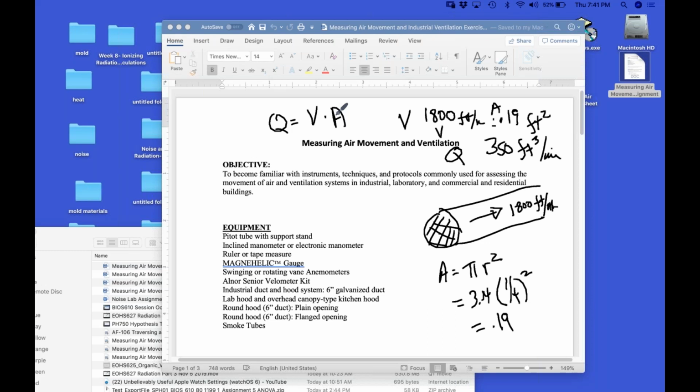Yes, so reading basically the same thing you did with the thermometer as we read with the vane. No, that was strange. And you know why that might be? The reason it might be happening is because you've got that big fist of yours and that big vane stuck in front of our duct work. So you are modifying the performance of this duct with those giant bits.